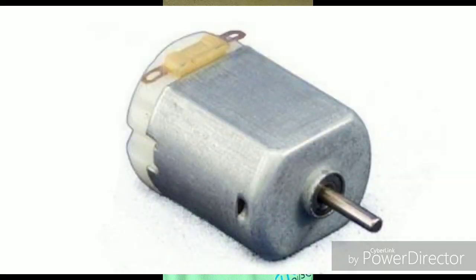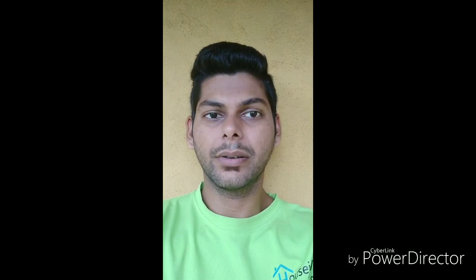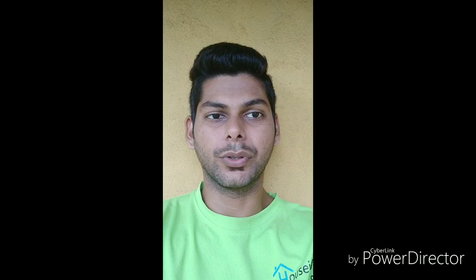I'll give you some notes on this project. The motor used in this project is a geared motor used for mobile robots, and the rotor speed is slow. The project is built using the 2N2222 transistor, which has a maximum current rating of 800 milliamperes, which is enough to drive low current motors.